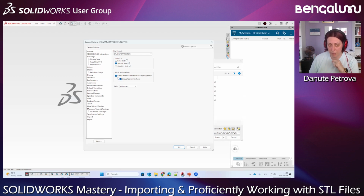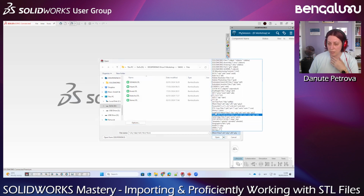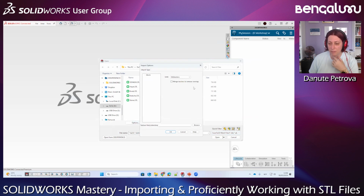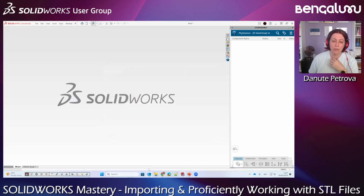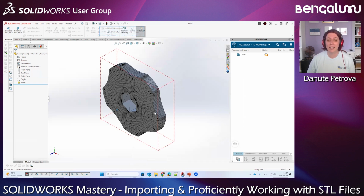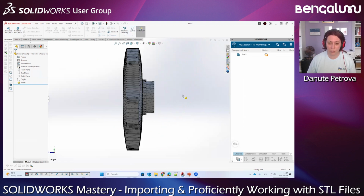And when I mark this, this becomes grayed out. You should uncheck it to have the option graphic body. For now, I will leave it away because we do want to use Scan to 3D. And here we have some other options which are not needed. So this is the file we want to use today. This nice knob, which I actually created for this tutorial, but I think it's a great example because you have a lot of complex shapes here.